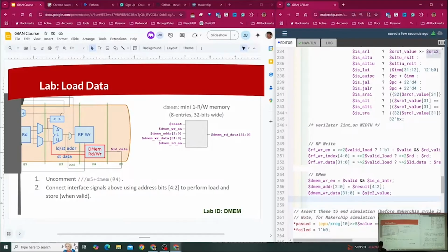And then the read enable. So reads are loads. So we're doing a read when we have a valid load instruction. Okay. So that's our inputs, and then our outputs. Only one. Sorry, it is load data. There we go. Which is going to be 32 bits. Should be hooked up to the read data.